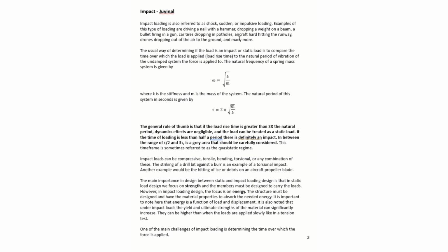So as stated here, the usual way of determining if the load is an impact load is to compare the time over which the load is applied to the natural frequency or the natural period of the system that you're applying the load to. Now, the natural frequency, we remember, is the frequency at which a system wants to respond when hit with a load or an impact and then allowed to freely vibrate.